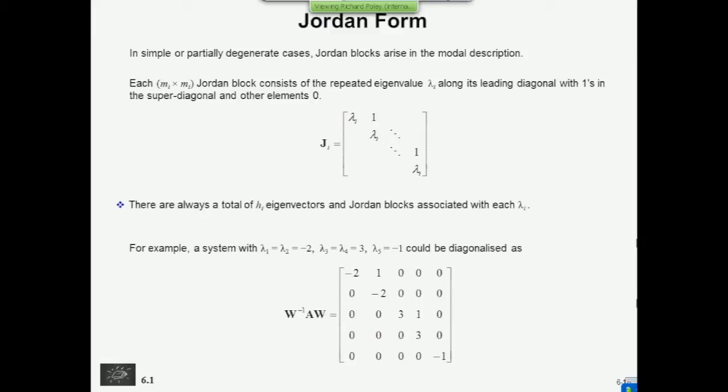Yes, exactly. Well, sort of. Yeah, you're right. But I want to get away from the idea of lead and lag compensators and also from root locus. Because with the system I described yesterday where we used output feedback, we were obliged to put the closed loop poles on specific lines in the complex plane called loci. And the only thing that we could change was the gain to move the poles along those loci.